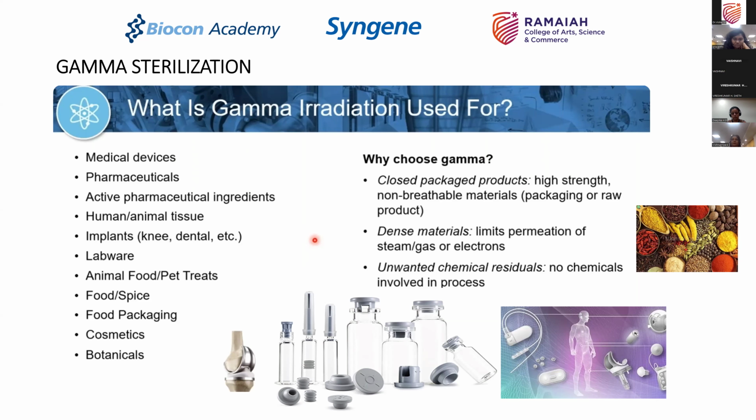Now, if you had to sterilize that using VHP or ETO as a gas, is it possible to penetrate that thick layer of Vicks VapoRub? Very difficult. You don't need to make Vicks VapoRub sterile, but if you wanted to, gamma irradiation is what you would choose, because it can penetrate through that highly viscous product. When bombarded from all sides, you will get a sterile gel out of that. So that is the reason why gamma irradiation has to be chosen carefully when used for pharmaceuticals.